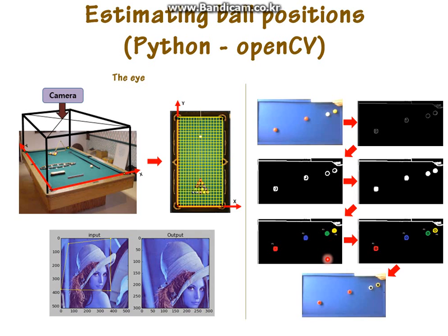Now we can get the center of mass position of the balls by tracking the gray image intensity. With the 4 ball center positions, we made a circle of 5 pixels radius at the center position of the balls, mapped the area into the original image, and extracted the BGR values to recognize the colors. In this way, we could get estimated ball positions.